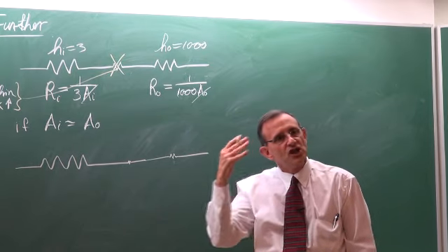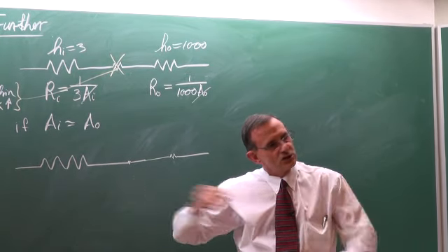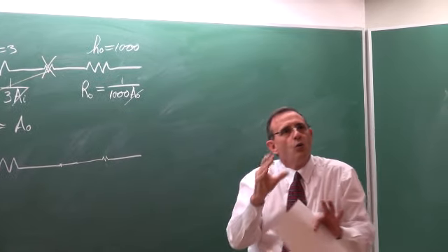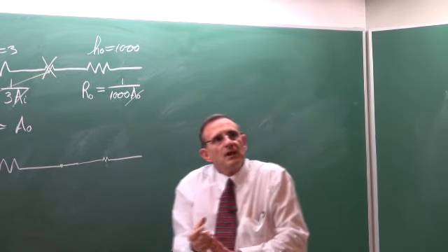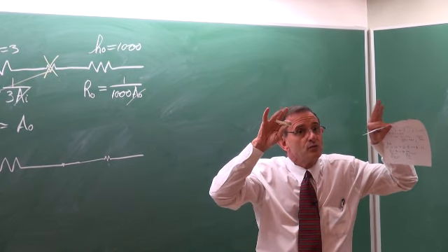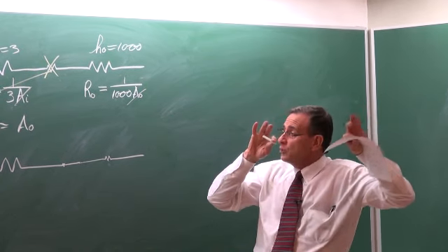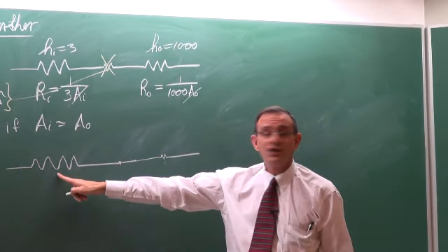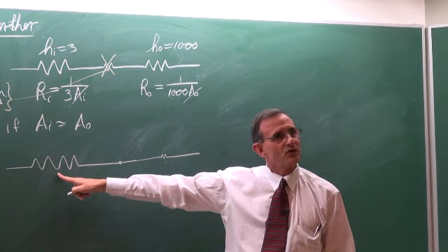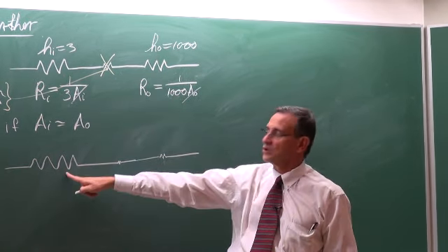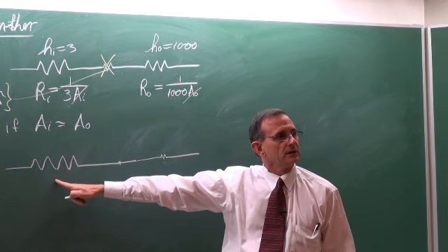So when you work with heat exchangers, you need to think about these things. It is not just calculations. You must try to understand where the resistance is and where the problem is, in terms of the bottleneck in the heat transfer. So we can see that if we want to transfer more heat, we actually need to decrease this resistance on the inside. Putting fins here on the outside is not going to help us. We must work on the inside.